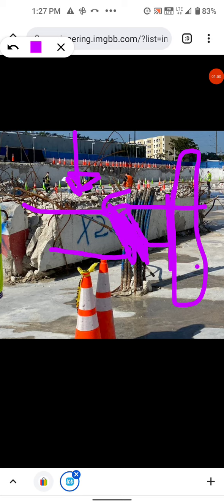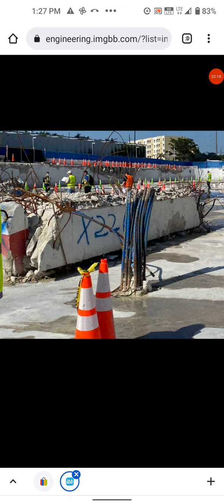For example, the steel just being overloaded, no deflection in the steel, but the bolts are the weakness of the system. So you get no deflection, but the bolts are the failure. And that would be the bolts over here, let's say. So you can get failure without deflection, although I didn't troll him and say anything to him. I figure he'll come around to that one day. He's just a professor, and he's got the same crazy mind I have. Not quite, but it's close.